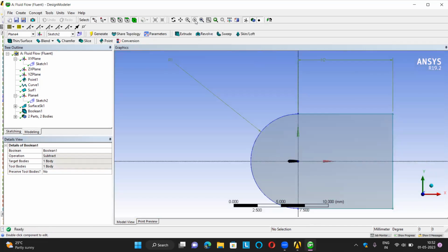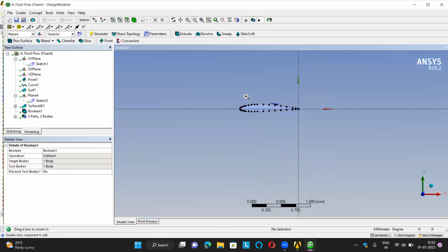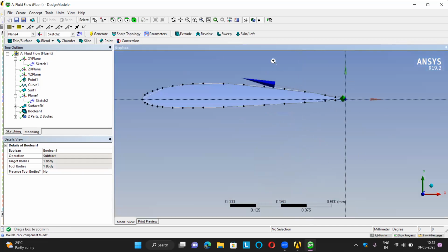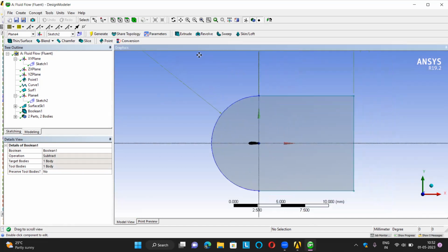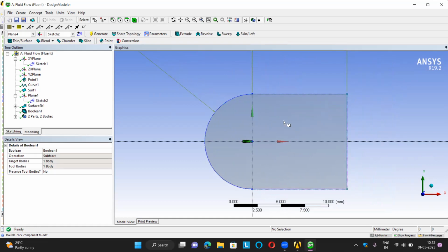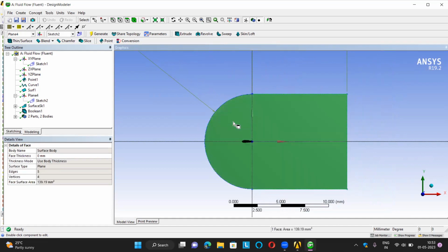The material in this airfoil is completely removed now. So after doing till here, the domain is generated, everything is done. But if we select the domain, it is selecting the whole domain, but we want individual domains. For that, I am separating the lines.